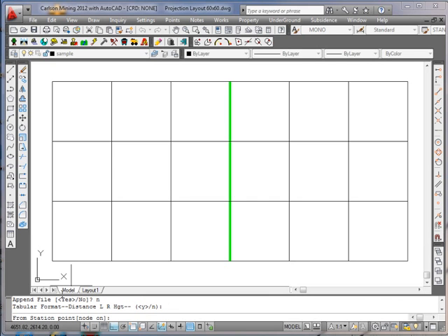And now we're prompted for the station point, a node on, and I'm going to set the snap, in this case, to the intersection, and indicate the direction. I'm in ortho mode. I'm just going to pick up here for the direction. I could type in the azimuth that I wanted to lay out this projection on. The entry number will be 1.